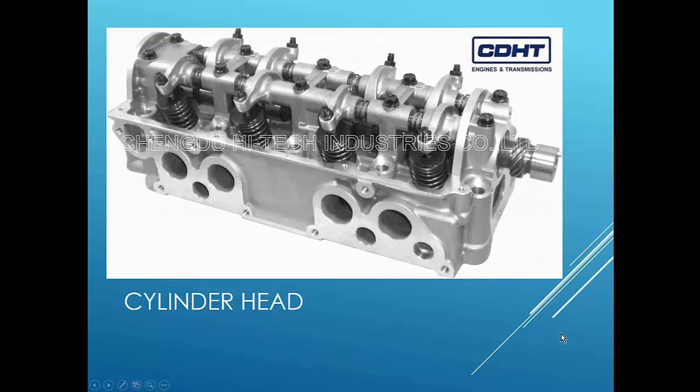Okay, and now on the top of the engine goes the cylinder head. Now this goes on top of the cylinders. Now inside of the cylinder head you've got the camshaft. And now to let in the gas and the air and to let out the exhaust you need to have valves. Now the cam on the top here is moving the valves.